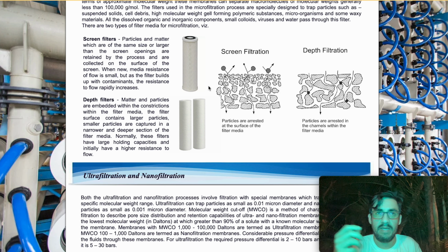So filter paper might be down to 0.2 or 0.02, 0.5 micron, and those sizes are for sterilization because they can remove bacteria and viruses at that size. This stuff is like way magnitude smaller than micron size, and we don't measure particles in size. We measure them by weight. So you can't really compare apples to apples, even though you can infer a few things, but hear me out. We talk in molecular weight.